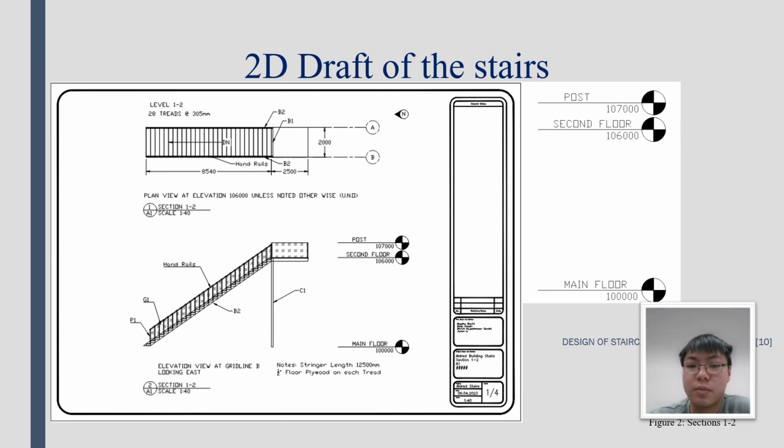The stairs will be 6 meters tall and are supported by a column under the landing, as you can see. The treads will have wood planks on top of them, and they can be replaced when needed. The stairs will have a post on the treads which is connected with the glass panels, and the handrail is 40 millimeters wide, and the angle of inclination is 35.